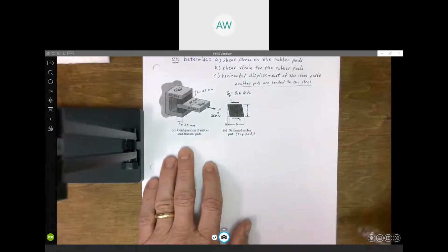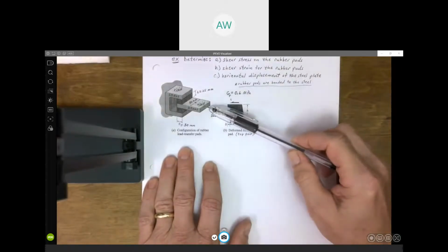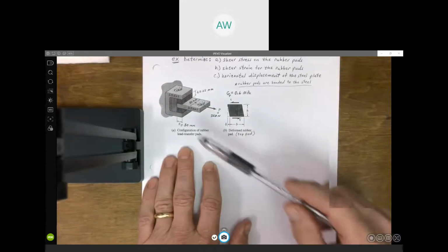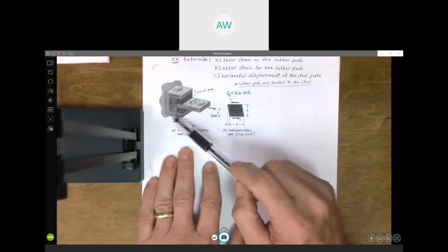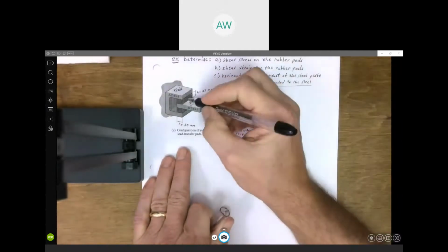When we apply the loads, it doesn't deform. We've got another, just a flat steel plate that is also assumed to be rigid, so it's not going to stretch. And that steel plate is attached to our C-shaped bracket here by making use of these two rubber pads.